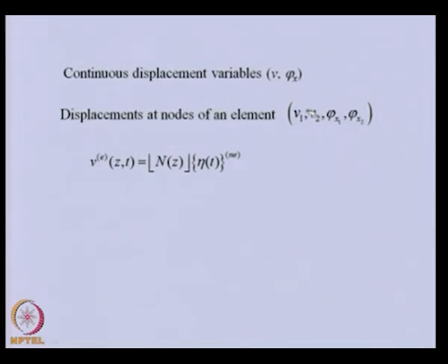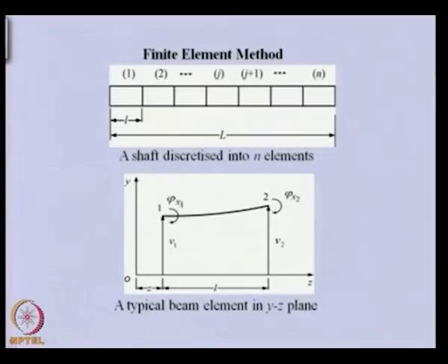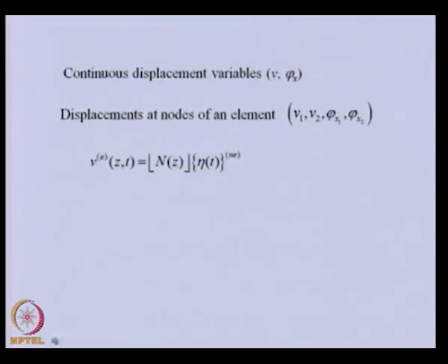These are the field variables for one element. So, 2 are translational and 2 are slope. Now, in the finite element method, we will be seeking solution for these displacements, and if we want to know the displacement at positions other than the nodes, then we will use an interpolation function or shape function to interpolate the values of the displacement in between.